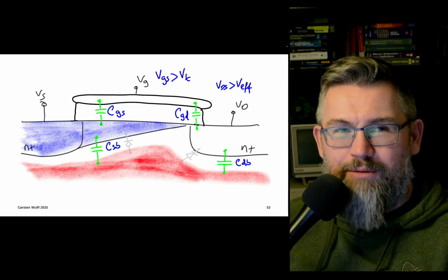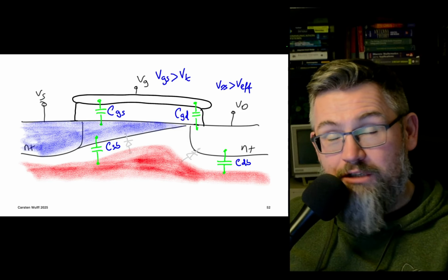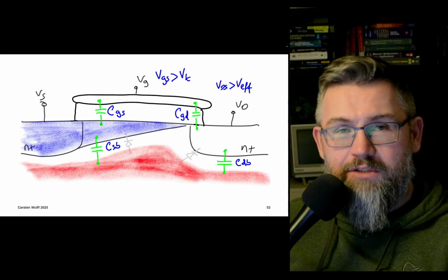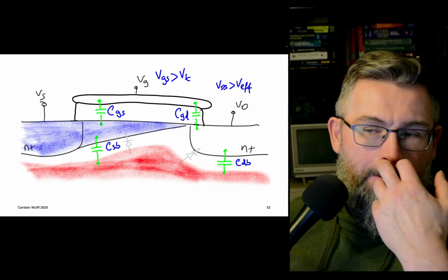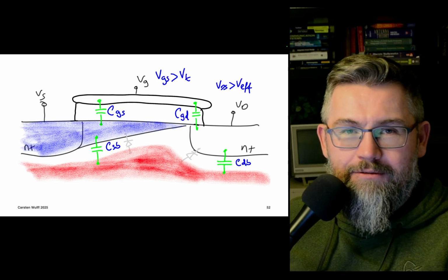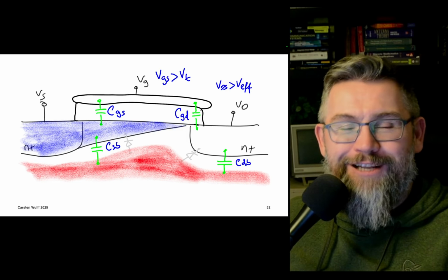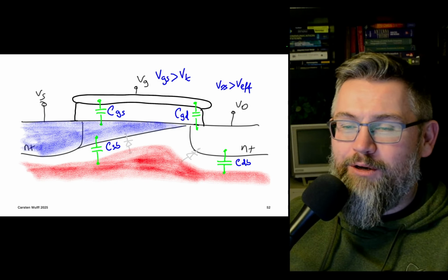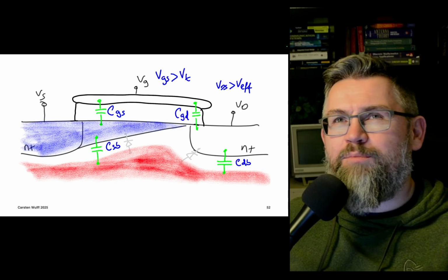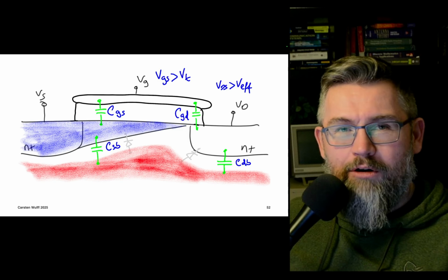Yeah, it's rare that we put up a full circuit with those, but you actually do have to do that if you want to compute the high frequency gain, for example, of an op-amp. Usually. Or you put it into the simulator and do it that way. But if you want to do it analytically, you can do it with the small signal models. Sometimes, though, like diff pair is better analyzed with the T model of a transistor.